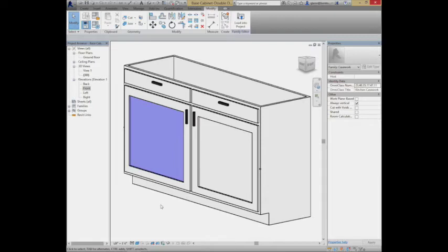They're pretty good. You're going to put parameters in there that control material. So you can choose the material of any object, whether you want it to be wood or glass or whatever it is. We'll add those kinds of parameters. A third kind of parameter I'll let you know about is one that just controls visibility. So for example, if you have a cabinet like this and you want to have a version that has handles, and another version that doesn't have handles, I could make two separate library parts, with handles and without handles. But you really don't need to do that because whether a handle is there or not could really just be a parameter.